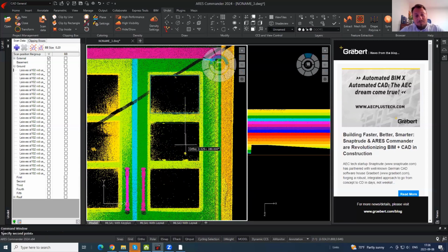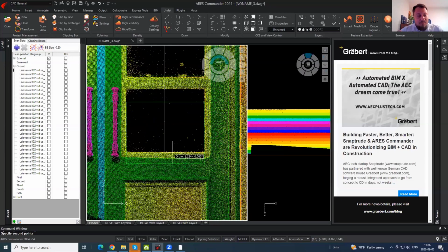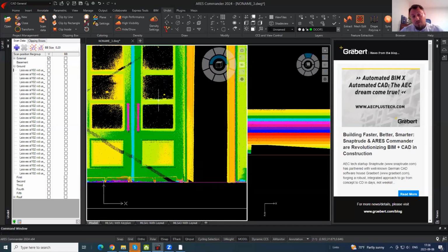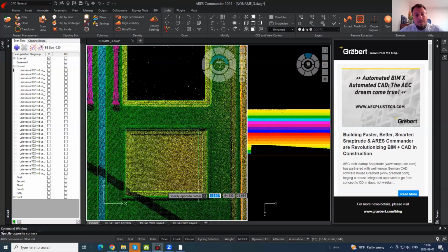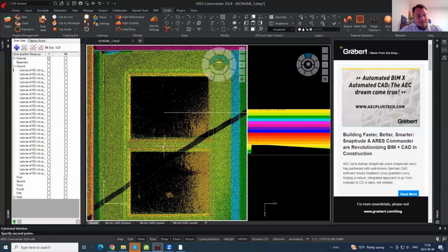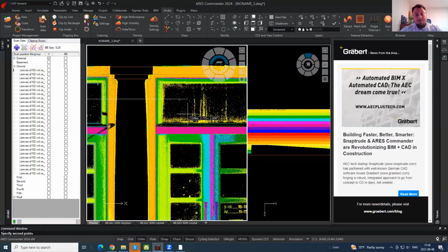So first of all, just slice the point cloud to see the entire view of your building and pick the nice looking windows which were scanned in great detail, usually from the first ground floor, and later on you can just copy them to the upper floors. And don't do the opposite, because you will spend a lot of time to vectorize the window, and later when you start to copy those windows, you will find some mistakes.